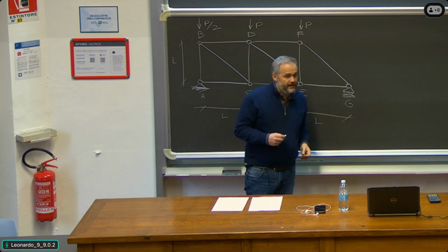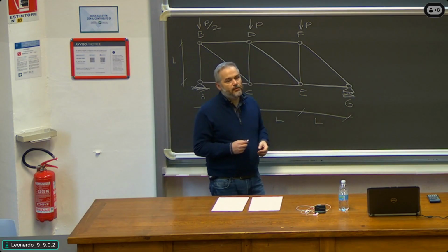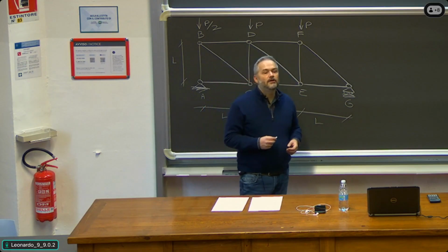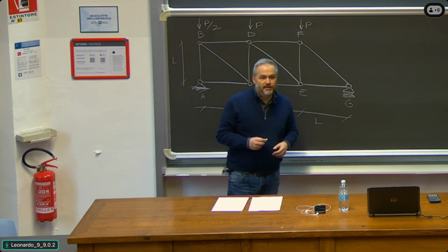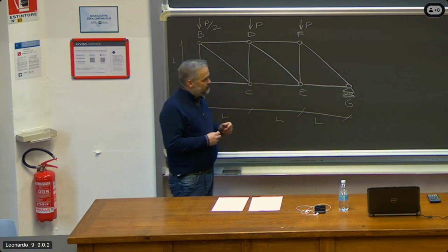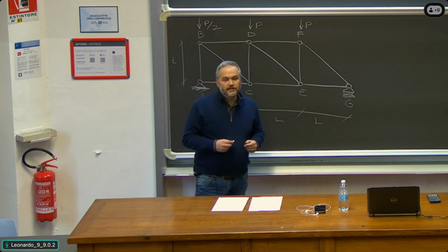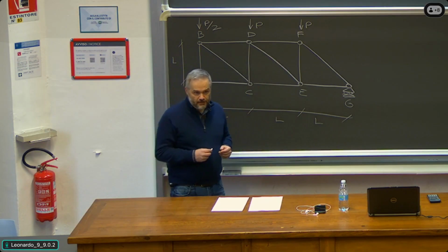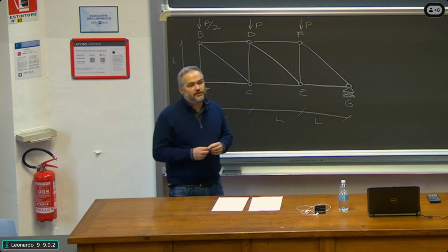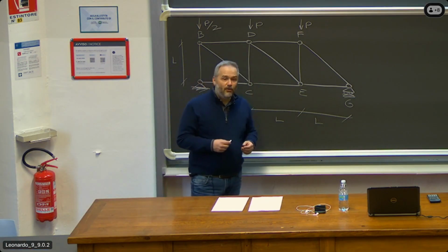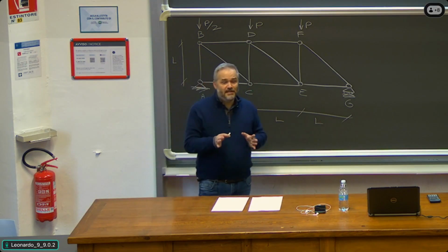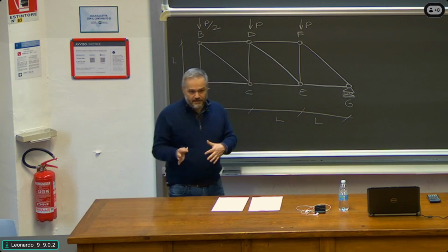As a matter of fact, when you have such a structure, the first requirement that should be fulfilled is rigid body equilibrium. So we have to work out a set of reaction forces which fulfills rigid body equilibrium. Besides, in such a structure, which is statically determinate because it has only 3 degrees of restraint, this set of reaction forces is unique. This is not the case when you have statically indeterminate structures. You can find infinite sets of reaction forces. Also, in that case, there is only one which fulfills at the same time rigid body equilibrium and compliance.